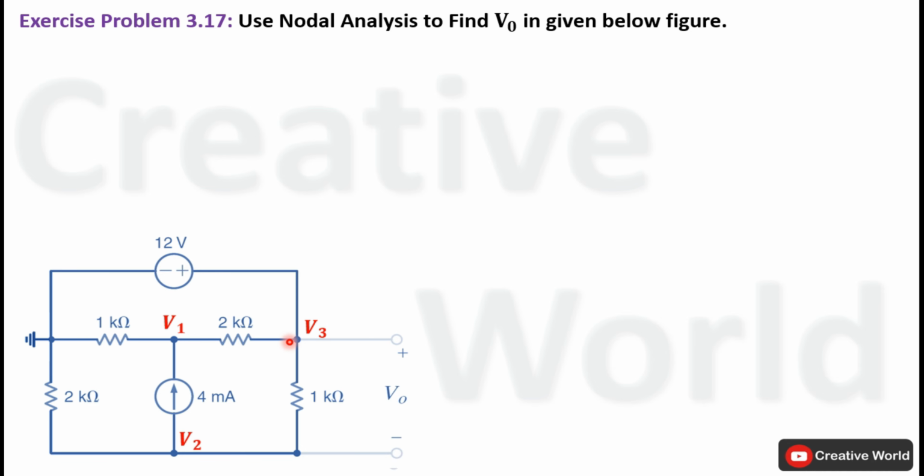So in order to restrict this solution only to nodal analysis, we have made this node the reference or ground node. Now this voltage source is not coming between two non-reference nodes, so the circuit can be solved using the simple nodal analysis technique. The other three non-reference node voltages are labeled as V1, V3 and V2.